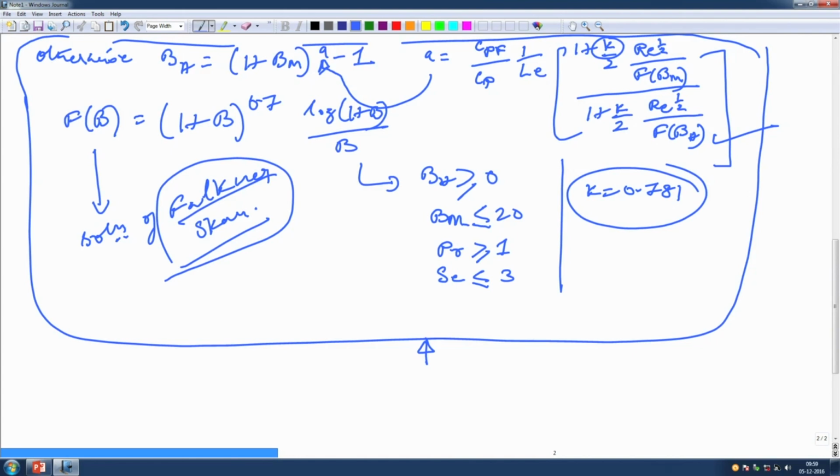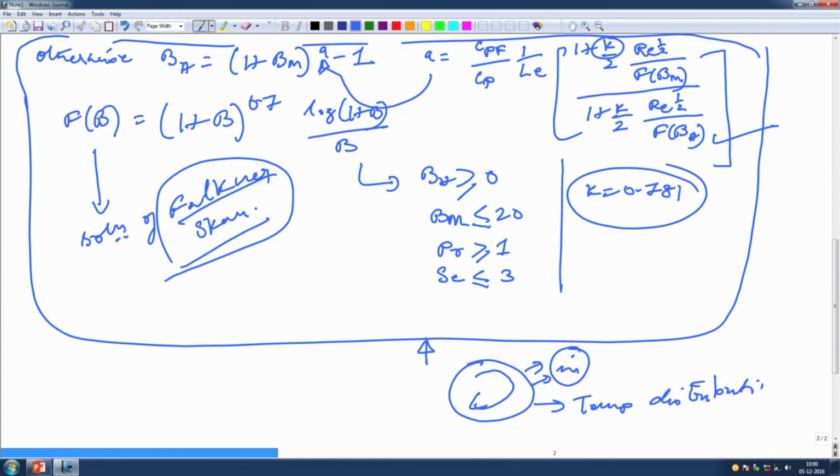People may be interested to know what is happening within the liquid phase itself. Why is that important? That is important in many things. Say, for example, you have a liquid, and you may not be just interested in that m dot. m dot is a global parameter. You may also want to know how the heat and mass transfer is happening within this droplet. That means what the temperature distribution is, and what the flow profiles look like. How does it vary during the droplet lifetime?